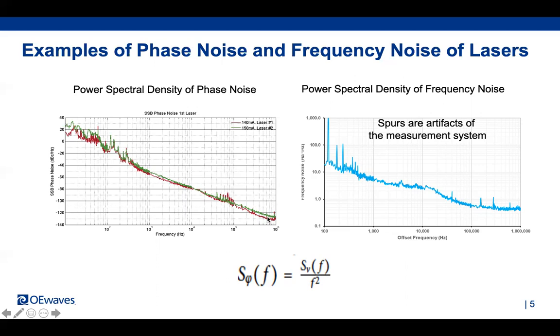For example, in the white noise region of the phase noise, if there's no other noise, you typically get the shot noise. But if there's amplitude noise in the laser, then those power fluctuations at the photodetector convert to phase noise, and they mask the shot noise. And so they indicate a larger noise level than the shot noise alone would give us.